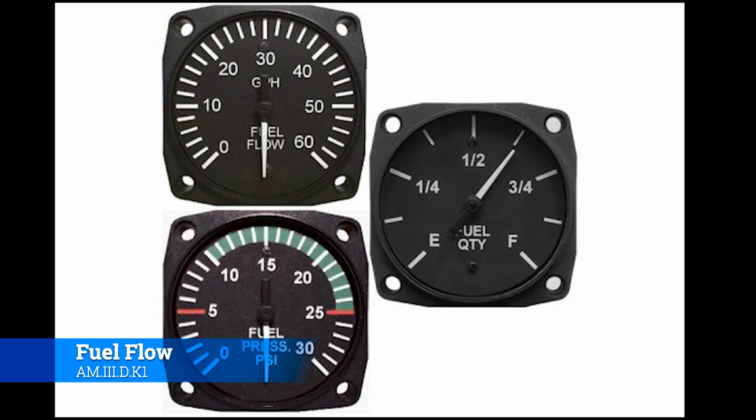You can infer then that the fuel is flowing, and you don't get quite the same amount of, I guess, fidelity as you would with the gallons per hour fuel flow meter, but it does let you know that the fuel pressure is there, so therefore we can kind of know that the fuel is moving through the line, so we get to the same point that we would with a gallons per hour meter.